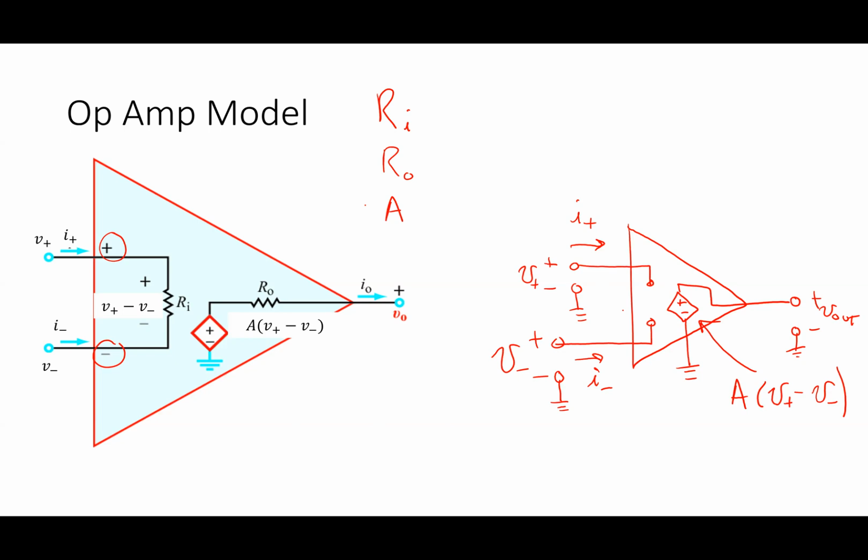We basically said that gain is super large, right? We said we approximate it to be infinite. All right. The output resistance there, 0. And the input resistance, basically what? Infinite. If that input resistance was infinite, we said, what's that mean about I plus and I minus, which I've defined to be the two currents going into the plus terminal and the minus terminal? They're equal to each other and they're equal to 0.